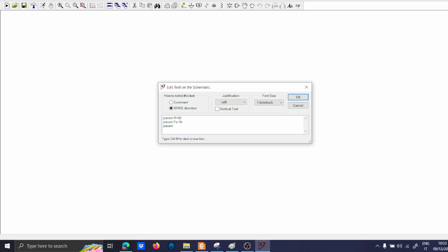And then we have the modulation, the triangular waveform, let's call it V3. Let us put it to 1, and then we have the modulation factor MA, 0.95. And of course, the control voltage of the sine, so it will be 0.5 times MA times V3.